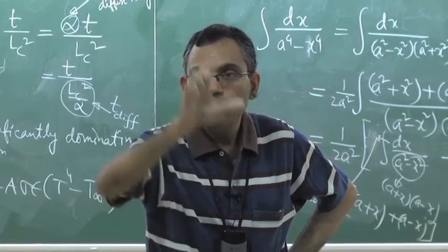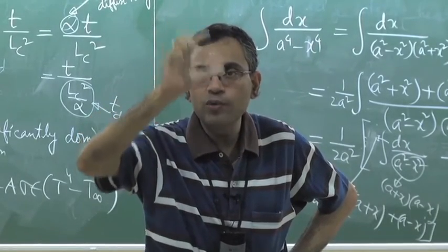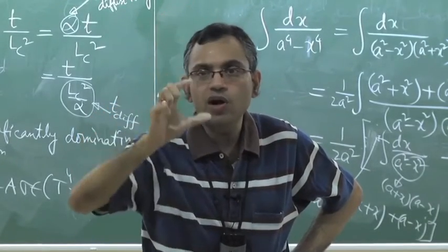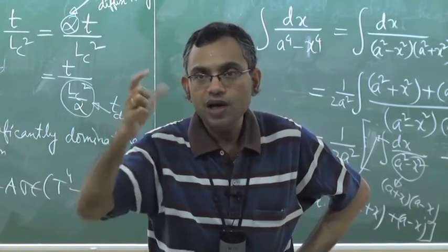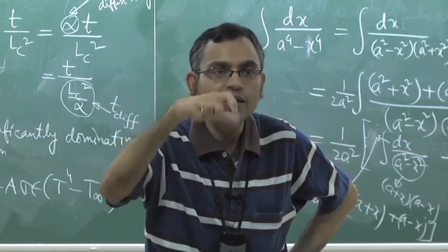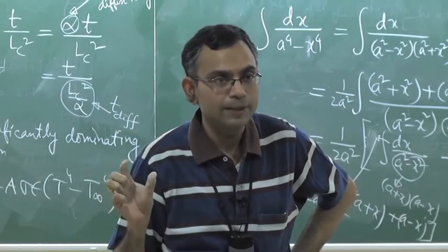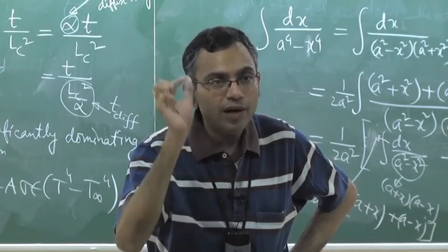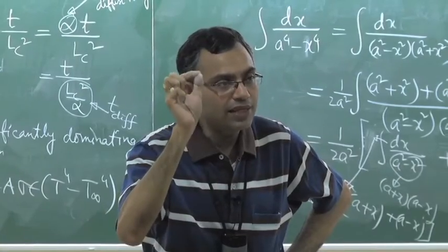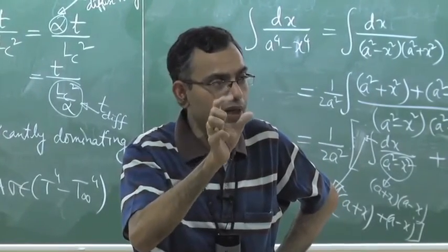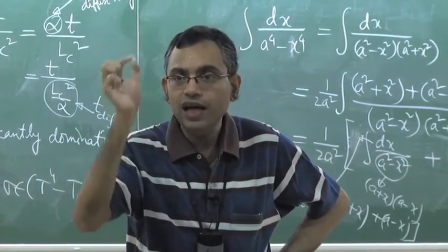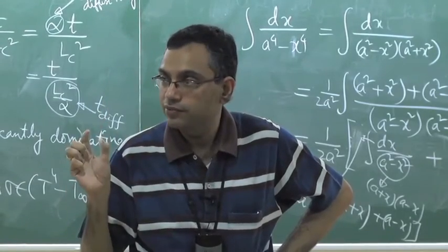So then whether the Biot number based on the volume and area is small or not is not important, because we have ensured by stirring that the milk is at a uniform temperature. So the requirement of Biot number much less than 1 is not a fundamental requirement. The fundamental requirement is the uniformity of temperature.